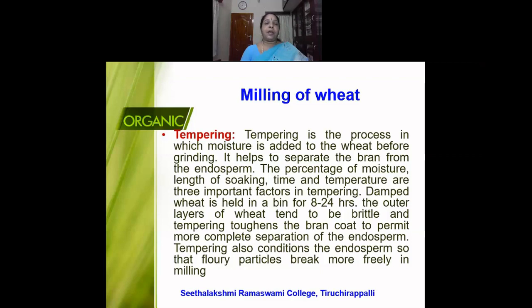So what will happen? Water is absorbed by the wheat grain and also the bran. The bran will become tough because water has been added and it can facilitate easy removal. Tempering will also condition the endosperm so that the floury particles break more freely during the milling process.